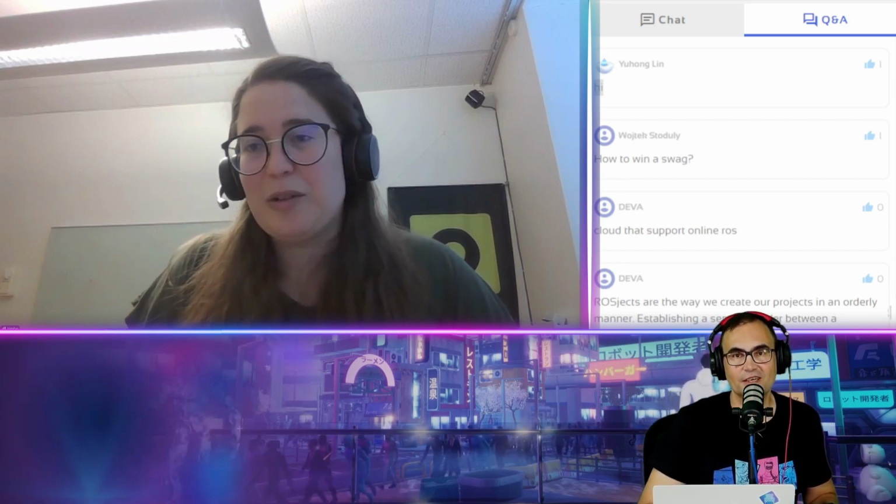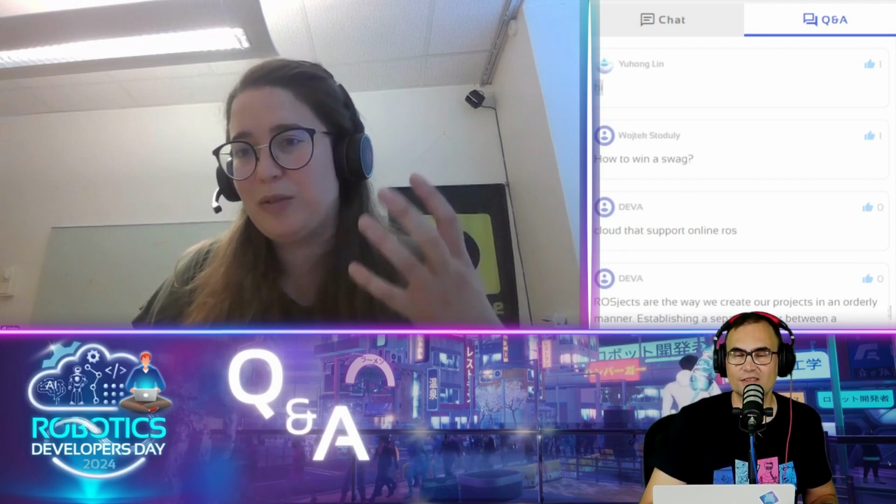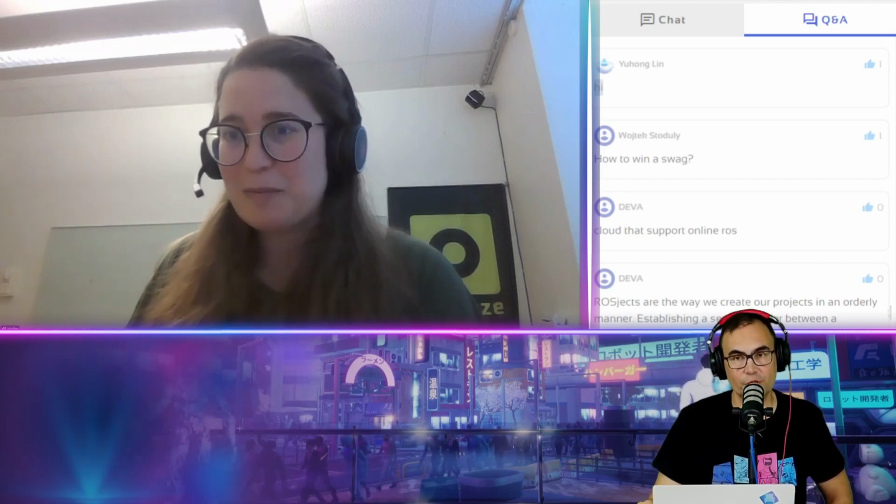So that is kind of the problem. You're not able to do really good localization. Luckily, I have a positioning system here, so that is not really a problem for me. But if you have a quadcopter flying in an actual real environment, without any predetermined knowledge, that's maybe a little bit more challenging. I see. So in this case, you are using the localization provided by your positioning system in order to create the map? That is kind of providing the odometry for the map building. But in SLAM, you have simultaneous localization and mapping. Right now it's pretty much only doing the mapping, but it's still fun.